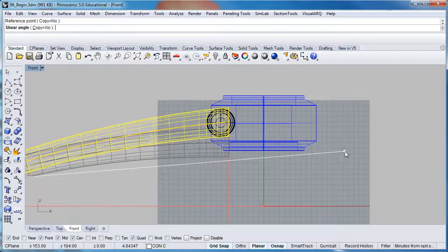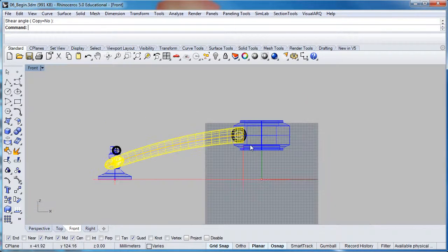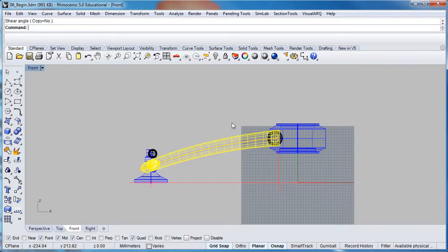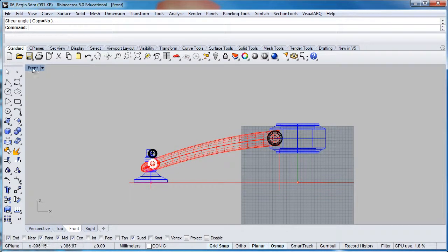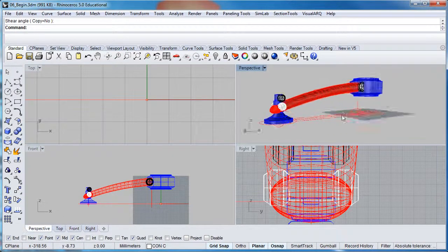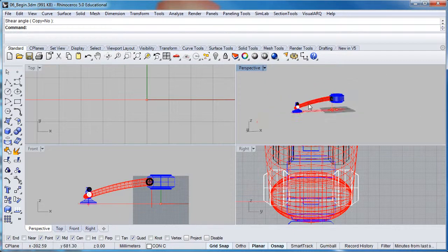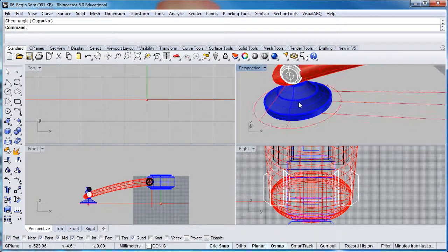We're dragging up the interface just slightly, and we're repositioning that leg such that it falls in the middle of the supporting ring. So that's looking quite nice. Double click on the front view to see the resultant effect. That's looking good. Now we need to add the holes in the bottom of the foot.